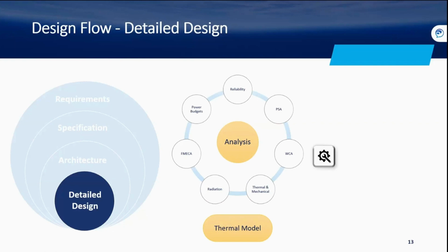Also, we perform the failure mode analysis, which basically consists of verifying that possible failures won't propagate outside the PPU to the rest of the system, and that we don't provoke overconsumptions. Also, we develop finite element models in order to provide analysis about radiation, thermal, and mechanical studies. And here you can also see the PSA, which is the part stress analysis.